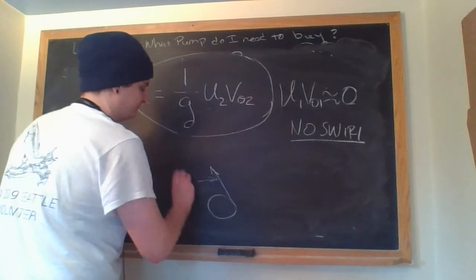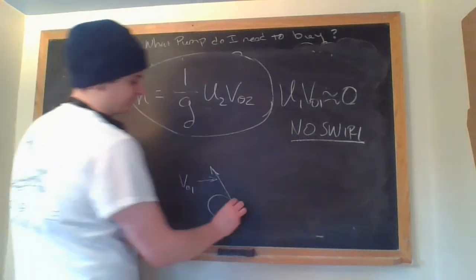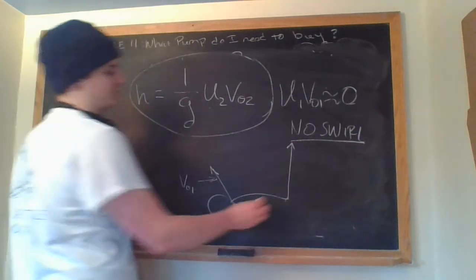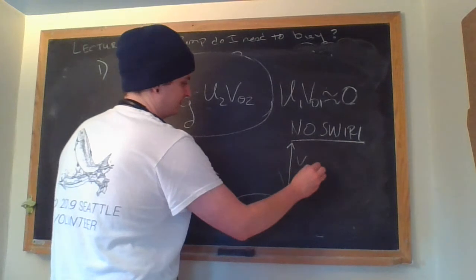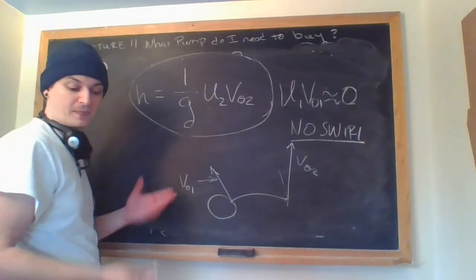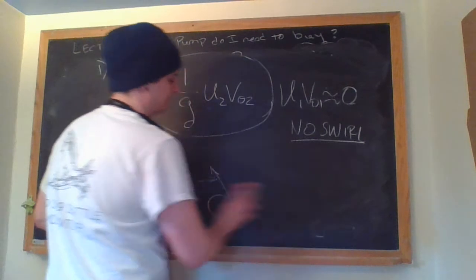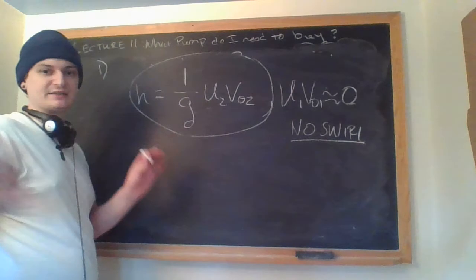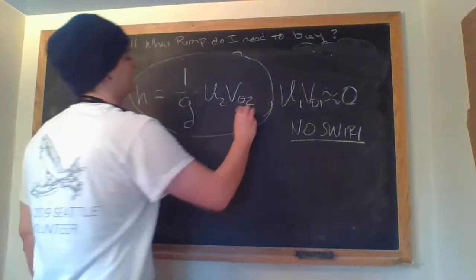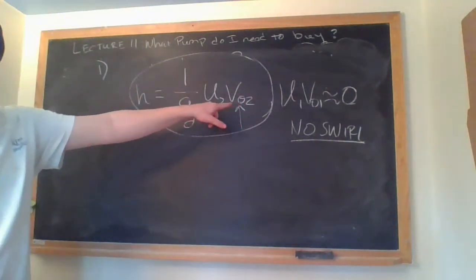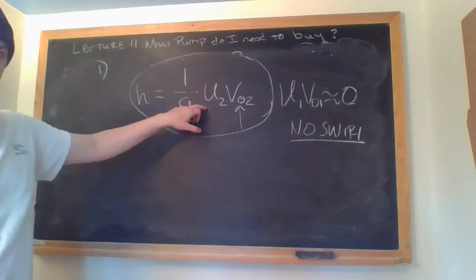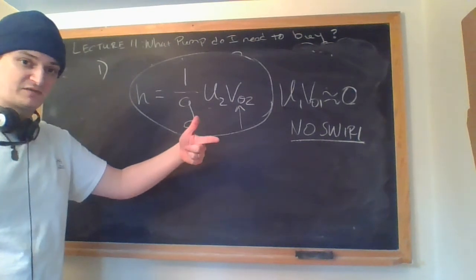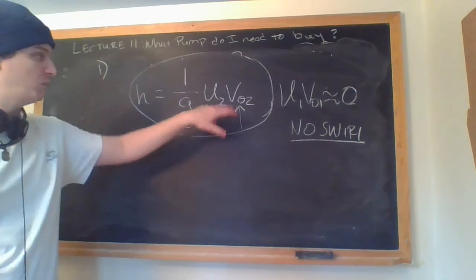theta. Once you get here, this is just going to be smaller tangentially than this one. You could look at the vector magnitude as well to derive the same result. But there was justification in this no swirl to at least ignore it, and then it was, how on earth do I describe this theta 2 velocity term? This one's not bad. It's an angular velocity and a radius. I can measure a radius. I can input power to convert to an angular velocity. I'm good there. But what about that thing?